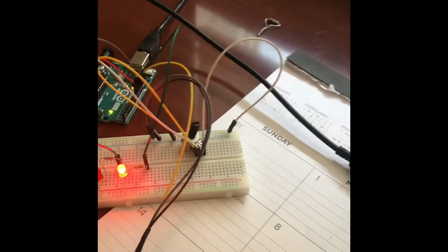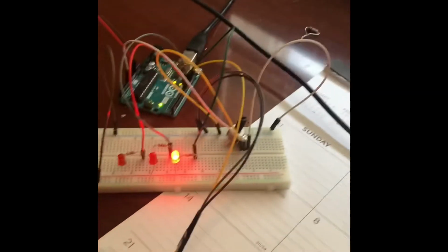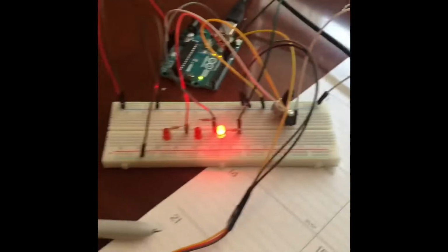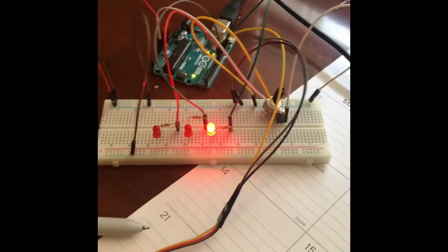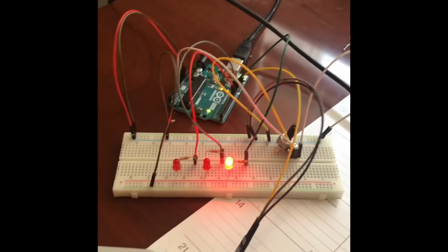It is connected to pin 13, which will take in the input that we get from the readings from the potentiometer at A0. It will output to pin 13, allowing the servo to move with the potentiometer. We also have 3 LEDs, which will start at 1, and then move across to the next and the next one as I spin the potentiometer.